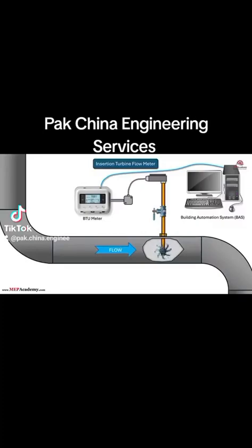These meters are inserted into the flow path rather than being in line, minimizing disruption to the system while making them more affordable. These meters are more commonly specified for HVAC projects for their ease of installation and their lower price. With the use of a hot tap, some of these flow meters can be installed into a pressurized and actively flowing pipe. The insertion turbine meter will require additional upstream and downstream straight pipe lengths than that required for the inline magnetic flow meter.